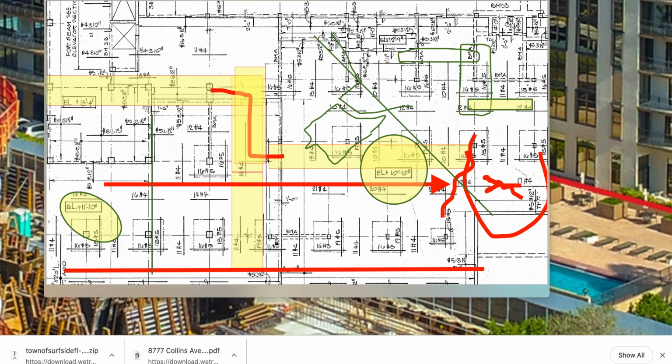They put another transfer beam to take quite a load here, so basically it would go there, and it was cheaper than building a column there. So their column layout was, let's put a column here because our span is now here to here.